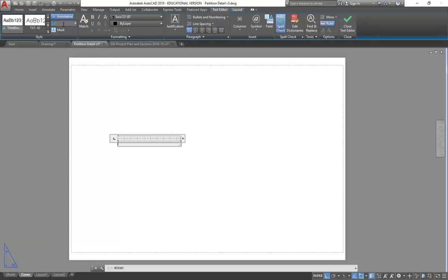Pretty much, yeah. It's a funny system. Well, it seems strange at first, but it's like that because if you later go and change the height of a text style, you don't want it to change all the text you've already done. Because in CAD drawings, or just in technical drawings generally, you're going to have lots of different text heights. And you don't want all of that to change every time you set up a new one for the future, if that makes sense. So I know it sounds strange, but it actually is like that for a reason.